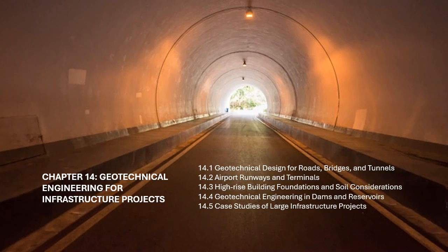Cutoff walls. A cutoff wall is an impermeable barrier, usually made of concrete or a mixture of soil and cement, which is placed deep in the foundation to prevent water from passing through. Cutoff walls are especially important for earthfill dams, where seepage through the core or foundation could compromise the structure's stability.